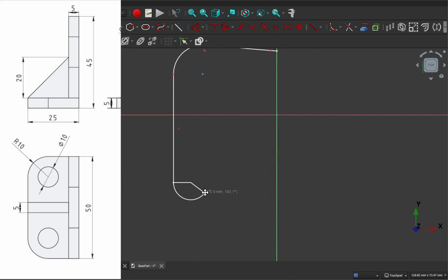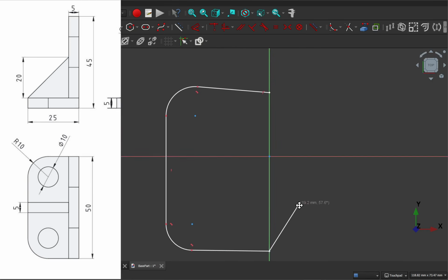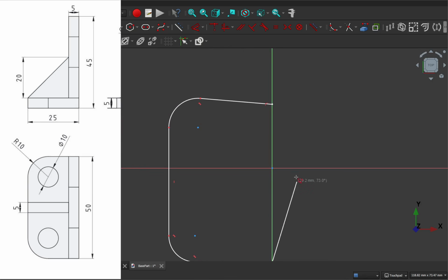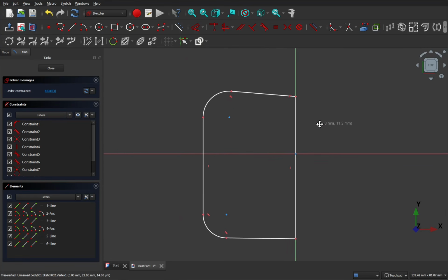Use the shortcuts to zoom and position the 3D view, and we look at the arc and notice the center point of the arc is where the two horizontal and vertical lines meet. So if they're at a right angle, then that's going to be a more tangent connection. I'm just going to leave the tangent line and connect up this vertical axis. And now it's automatically gone to a line. Adjust the 3D view and connect up this point here with a coincident constraint, close in our geometry, create a profile.